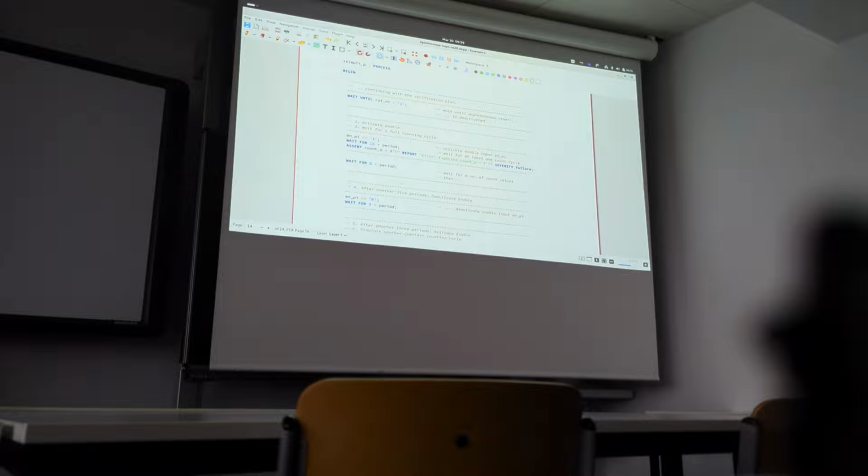Then wait for another 5 periods just to check that the enable works. So after 5 periods, wait another 3 periods and activate the enable again, wait for another cycle, and then if you count consequently, then we should get a 3, because we have our enable introduced, which kept our counter waiting for some cycles.